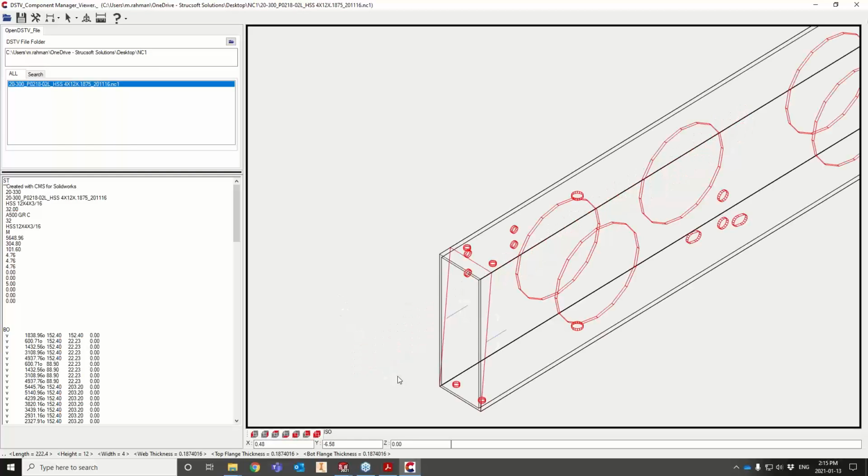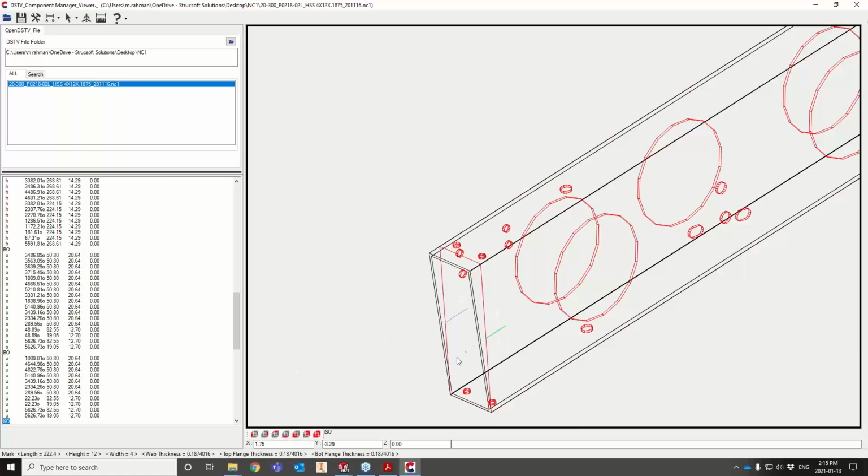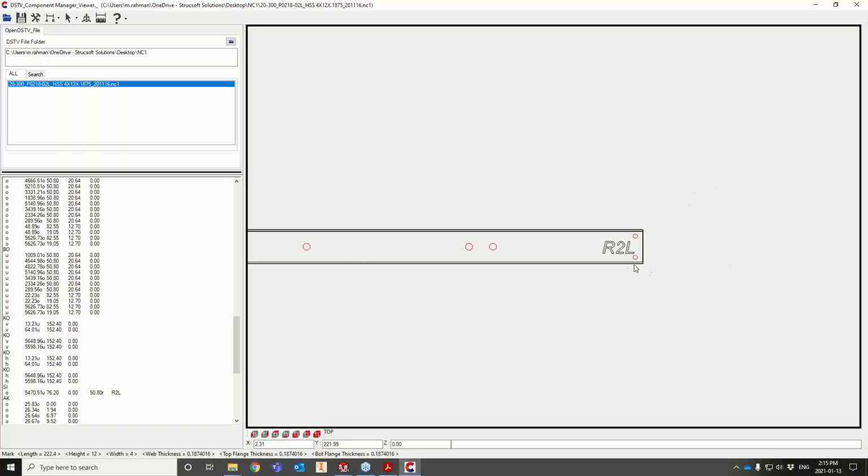As I see, there's a bunch of drills. I had a miter over here as well. Those are marking blocks, as you see. Once I click on that line here, it comes up as a KO block. So KO is for marking lines, right? If I go to my top flange view here and zoom in, as you see, this is the text stenciling that I had. Only one text stenciling document is on the line, and I deleted the other ones, just to show you that quickly.